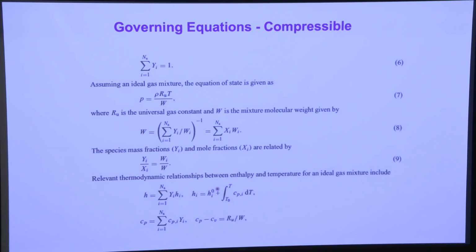And the enthalpies are given in terms of the sensible enthalpy, this integral of the specific heat of a given species at constant pressure integrated over temperature, and then the enthalpy of formation is denoted here by H_I naught of a given species at a temperature T naught.